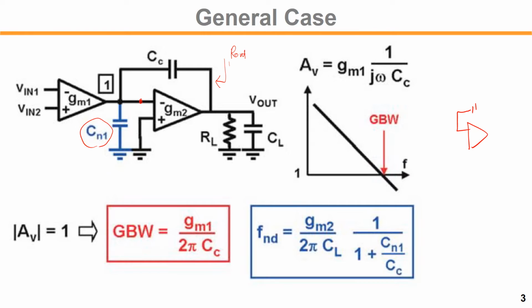Previously, with only the capacitor, we treated that as a short connection, because the input is infinite impedance, so no current flows through the capacitor, meaning zero voltage drop. It looks like a short connection, right?